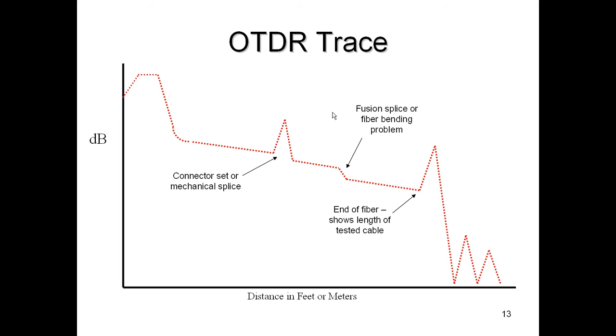You typically would use a build-out box, but what you get in an OTDR trace is what you see here. If we look over here on the left and start checking it out, the first thing you're going to see in an OTDR trace is a big hump, and this is called the dead zone. OTDRs use lasers only, whether it's a multi-mode or single-mode OTDR. And the laser signal, when it's pulsing out of the OTDR, the first thing it hits is the connector end that's plugged into the OTDR itself. This gives us reflection, and that reflection creates what we call this initial dead zone, this initial hump that you see over on the left-hand side. Then that curls down and comes into a flat area, and we call this the backscatter area.